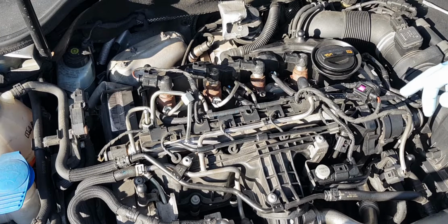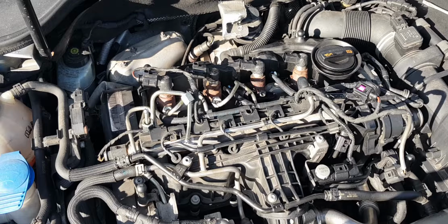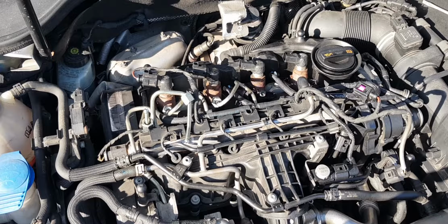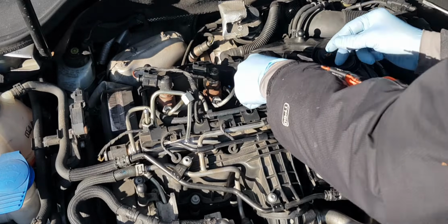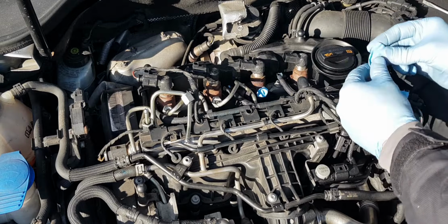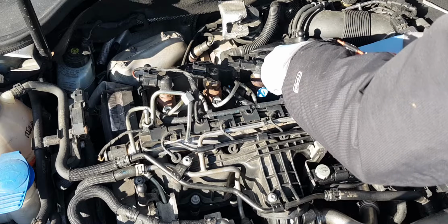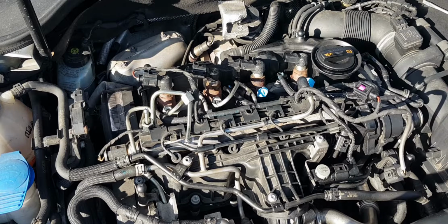It probably will be a good idea to cover these injectors with something, so I might try and find something for that as well. Maybe another tip from a rubber glove. So I'll be back in a second to cover these as well. So I'm back again. I've cut these tips. I'm going to cover them. Don't want to get any dust in them. And I've also cut one more for the newish injector that I'm going to be installing.